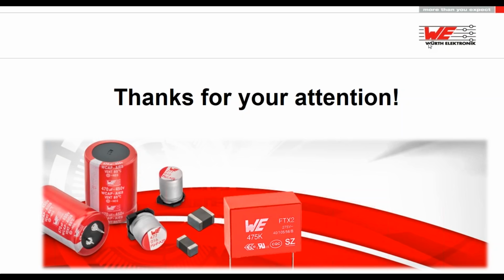Film capacitors are very stable, but you don't get the range of capacitance. So in comparison to some E-caps, for some particular applications, you even cannot go for film caps. And MLCCs can be a pretty good choice, because you can run them with a pick and place machine and everything. But they're good if you keep in mind the effects we talked about today, because otherwise you can really have scenarios within the application. You did your calculations with a 22 micro filter design, and then you take a 22 micro, bring it into the application, and it's just 10 or something, and the filter does not work properly because you didn't do your filter calculation with 10 micro.